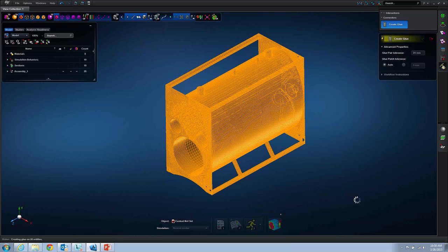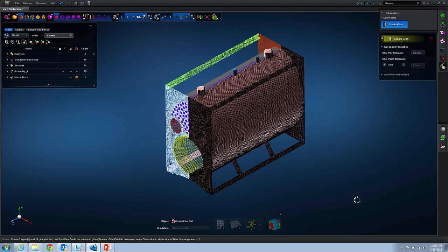And from the end user point of view, there are a couple of things one could do. I would have liked to equivalence all of the half of the model that we brought in, so that it is still 19 parts, but each of them is congruently equivalenced. And for the other half, instead of creating one part, I could have kept the solid bodies as is, and extracted the thickness from all those solid bodies into that one sheet body that we created. So there are multiple ways that one can slice and dice depending on the analysis intent, but in this case I chose this option to show the capabilities that we have in MSC Apex.